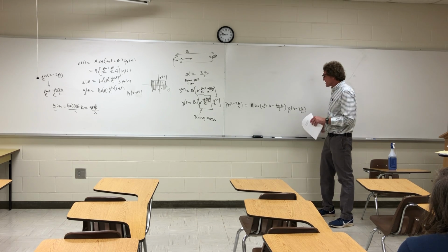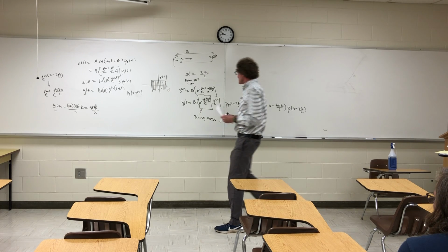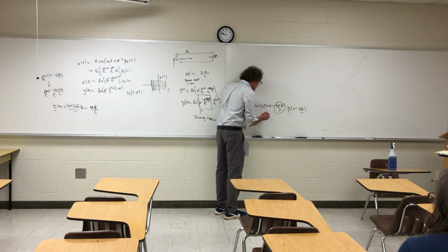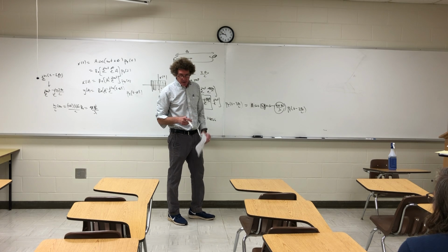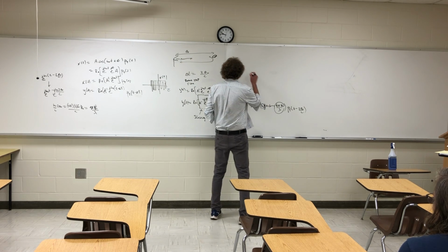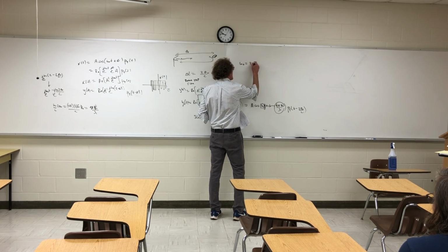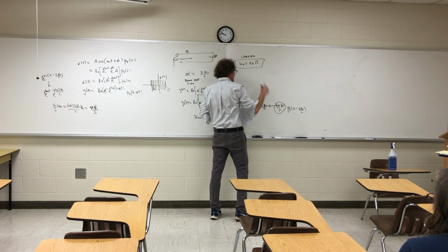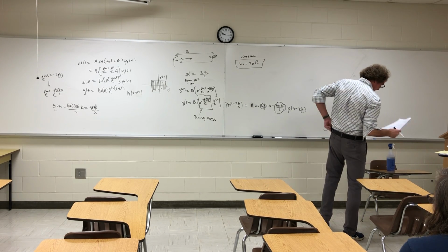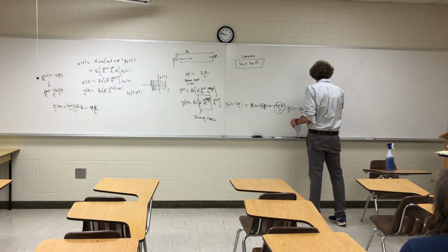So when I get down to this point, I'm really not saying too much other than what I can do is break out things that are slowly varying, this, and things that are fast, they're varying at the frequency. This is the actual carrier frequency, omega naught. Now he doesn't put omega naught in there, he puts 2 pi f naught, but there's no reason to, in my opinion. Omega naught is equal to 2 pi f naught, and that's the carrier frequency.